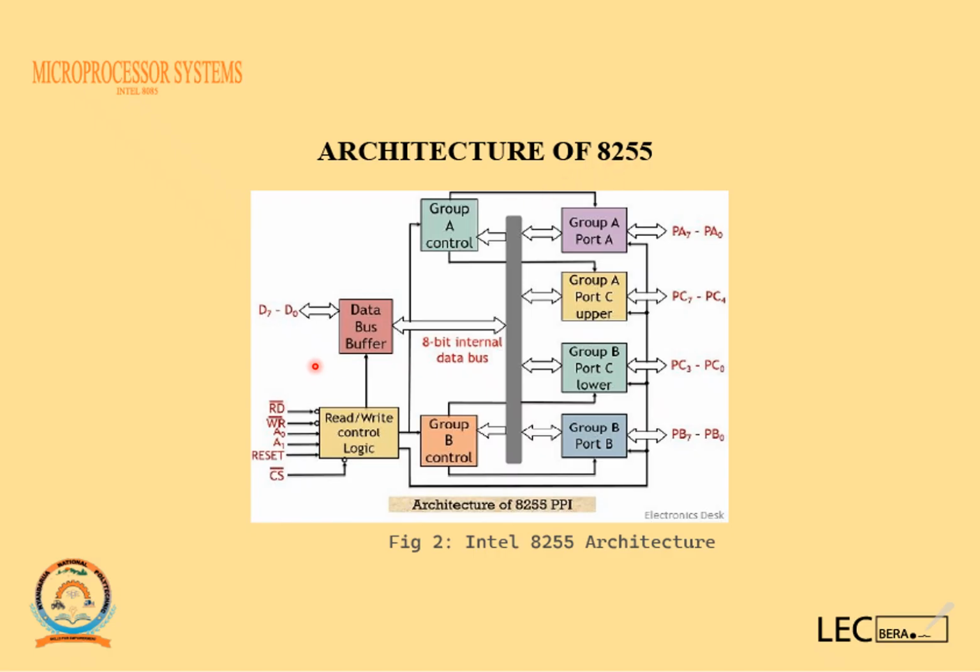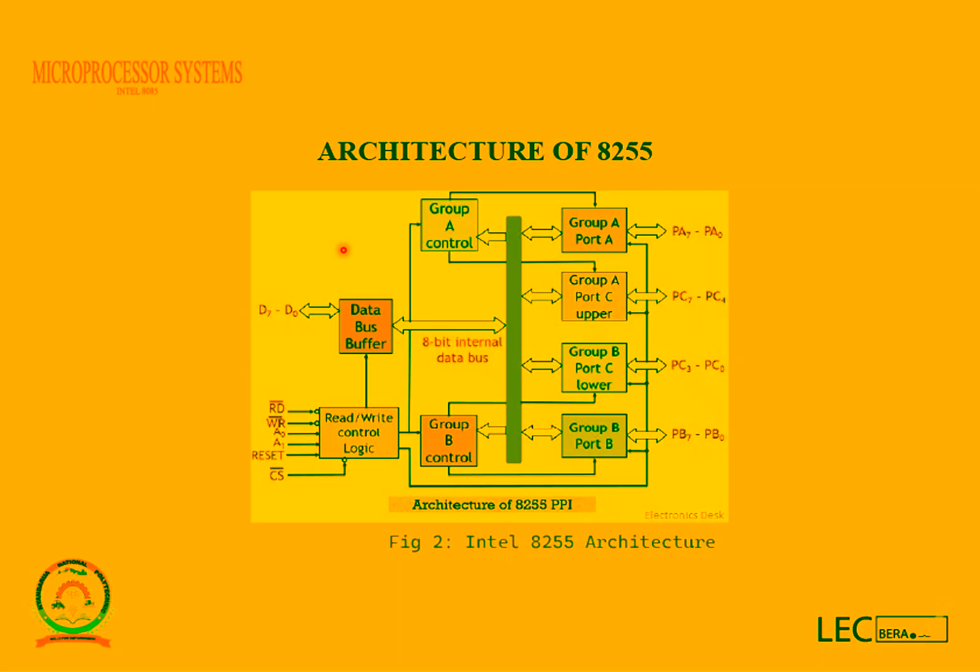The Intel 8085 can carry 8-bit data at a time, because its data bus has only 8 lines. Each wire can carry a bit, so with parallel transmission we carry 8 bits at a time. That's how we say it's an 8-bit microprocessor.